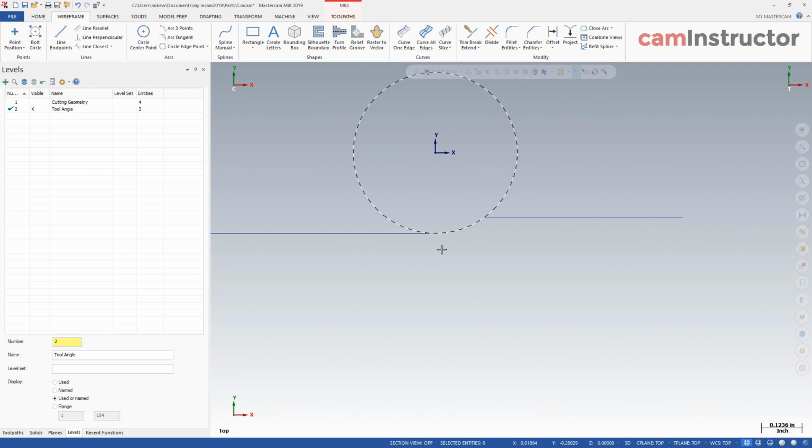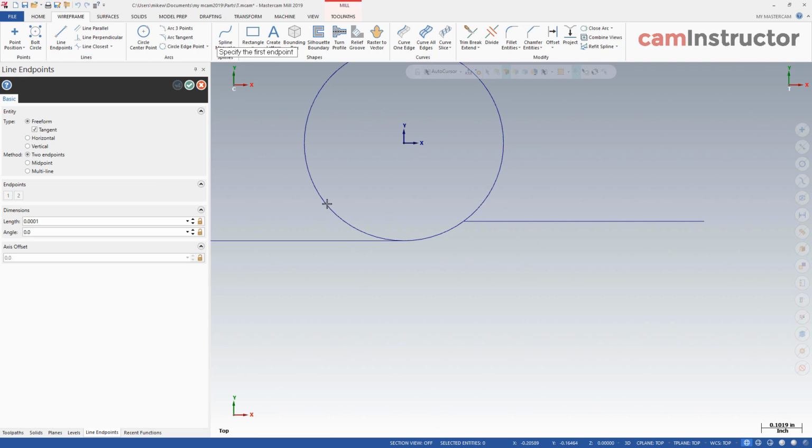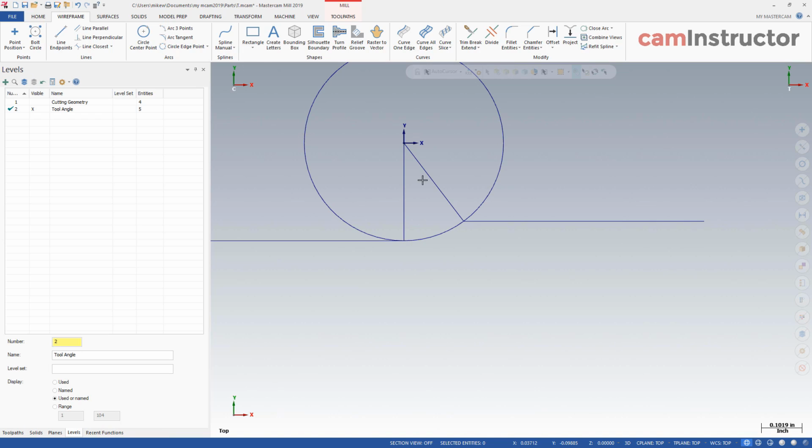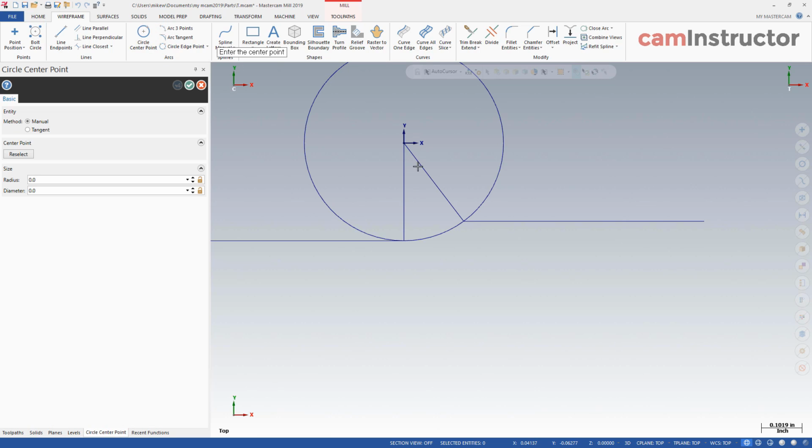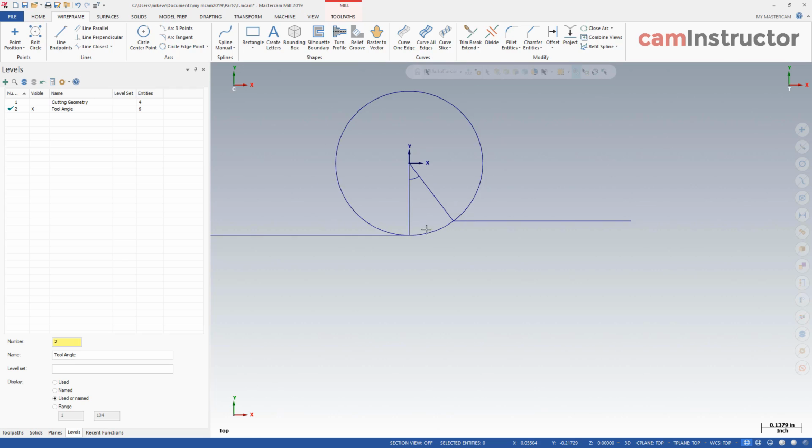Okay, so basically what's happening in our cut is with a 50 thou step over, this is the portion of the tool that's engaged in the cut. And we do typically talk about that as an engagement angle. So I can draw a line from the center of the cutter that contacts the actual material we're engaging. And I can draw a line from the center of the cutter to the end of the cut. So what was cut. So this angle right here is what's referred to as the angle of engagement of this cutter. Let me just make this a little bit fancier. Okay, so that's the angle we're referring to in there.